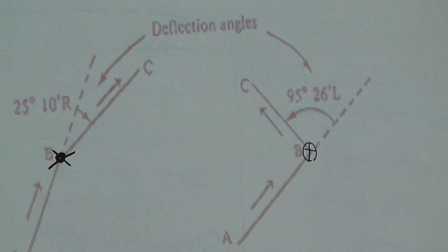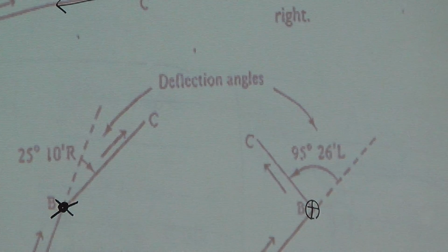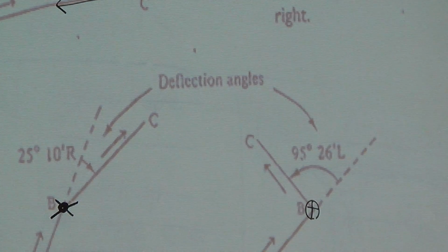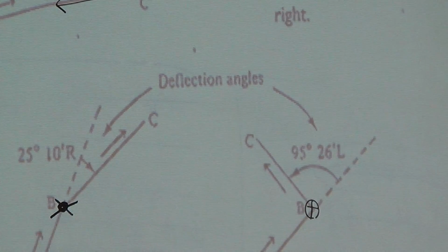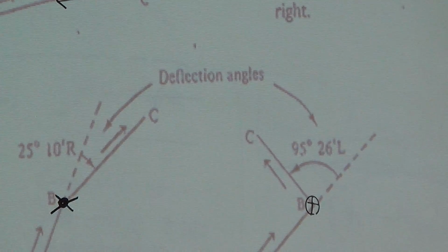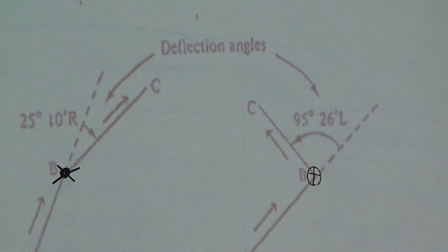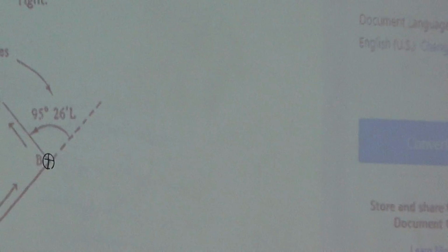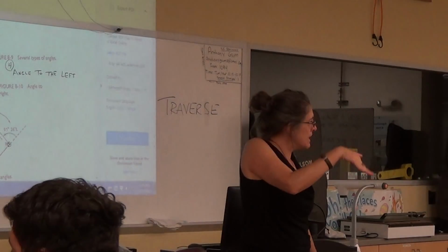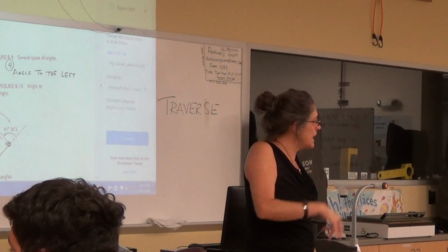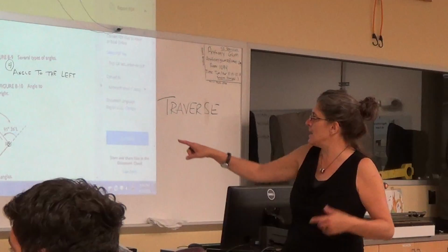What's really cool with surveying equipment? Now with the level, a level really can only be level. You can't turn it. But I don't know if you touched the total station that we had out, the theodolite, you could actually spin it. There's a telescope on top, right? It's connected here and you can just spin it around. Well, it's got to move because you have to be able to measure a vertical angle, right?